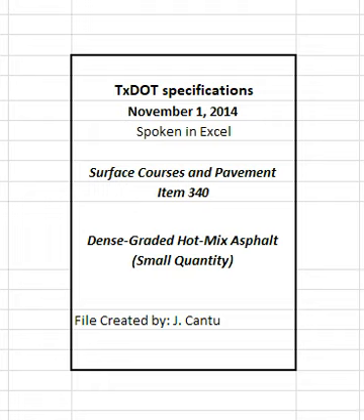Furnish a mix design report, JMF1, with representative samples of all component materials and request approval to produce the trial batch. Provide approximately 10,000 g of the design mixture and request that the department perform the Hamburg wheel test if opting to have the department perform the test. The engineer will verify JMF1 based on plant-produced mixture from the trial batch unless otherwise determined. The engineer may accept an existing mixture design previously used on a department project and may waive the trial batch to verify JMF1. Provide split samples of the mixtures and blank samples used to determine the ignition oven correction factors.